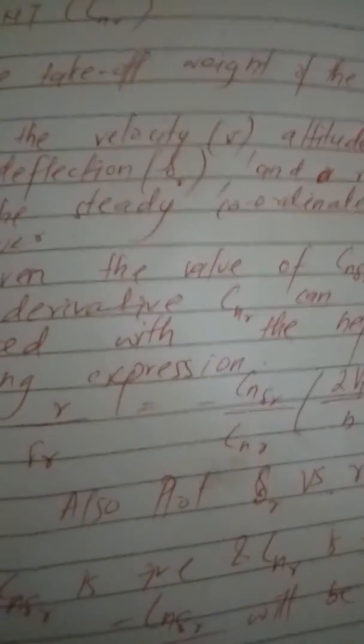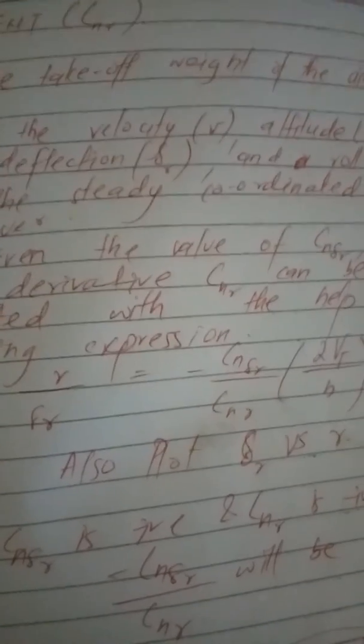So, flight test to estimate yawing moment. Okay, we need to actually test this equation. The assumptions are mostly zero: beta is 0, r is 0, p is 0. We have to consider how we are going to relate our assumptions to a flight test, and what the possible steps are, so that the assumptions we took initially stand during the whole flight test, from the start until the landing phase.